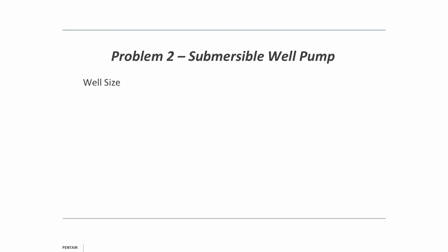Okay, so now let's look at another example here. We have a submersible well pump. Again, we have a 6-inch well, which is great. It means we can put in a 4-inch very handily in there. More importantly, the static water table is at 150 feet. Your drawdown is at 75. And again, the customer says the drawdown was tested well above the demand. I asked how well above. He said, well, we don't have an exact number, but we know it's more than we need.